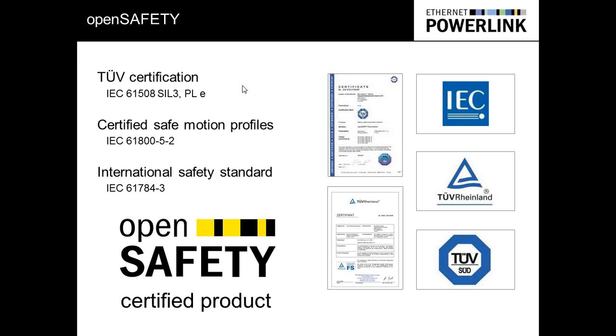And then there is a layer on top of POWERLINK called Open Safety. It's an open source standard. It's completely divorced from POWERLINK, but it will run on POWERLINK. And it allows safe communication between two components. So if you're trying to do a TÜV certified machine that you're going to be shipping to Europe, you can grab the Open Safety Stack, which is also maintained by the Ethernet POWERLINK Standardization Group. And it's already been TÜV certified, so you can just use it.